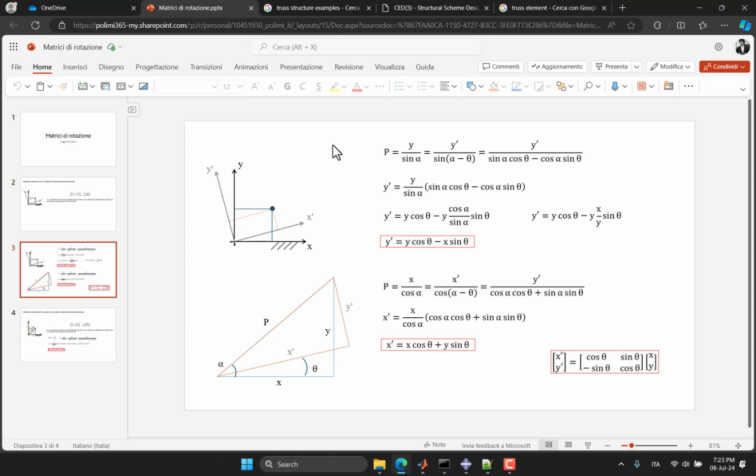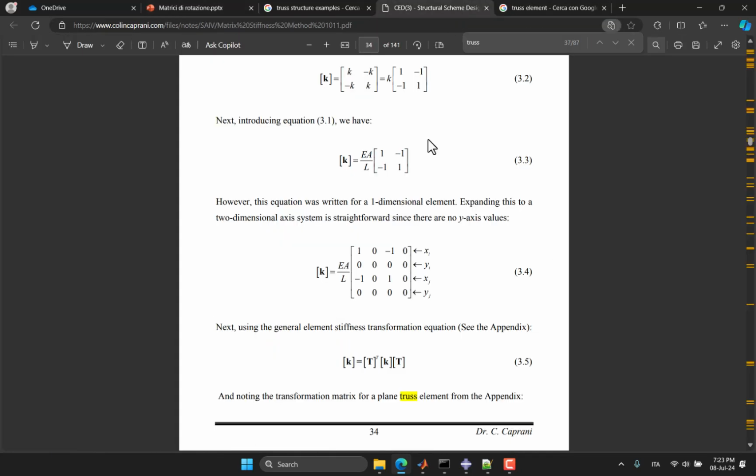From this equivalence you get this common expression: the stiffness matrix, which you can see as a transformation matrix in one of the two reference frames, is equal to the same transformation matrix K, rotated, pre-multiplied by a rotation matrix transposed and post-multiplied by a rotation matrix not transposed. This is basic linear algebra. This is not the topic of this lecture.